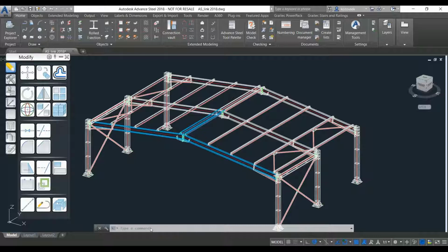Just start the Revit here in the meantime. Okay, so this is how it looks now in IDEA. We have the software set so that you work in, let's say, 3 steps: geometry, load effects, and design here in the menu. And if you go through those 3 steps, you are ready to calculate the joint. And since we imported the geometry from Advanced Steel, the geometry is all set here. So we have all those 4 members here imported, so there's nothing to do for us.